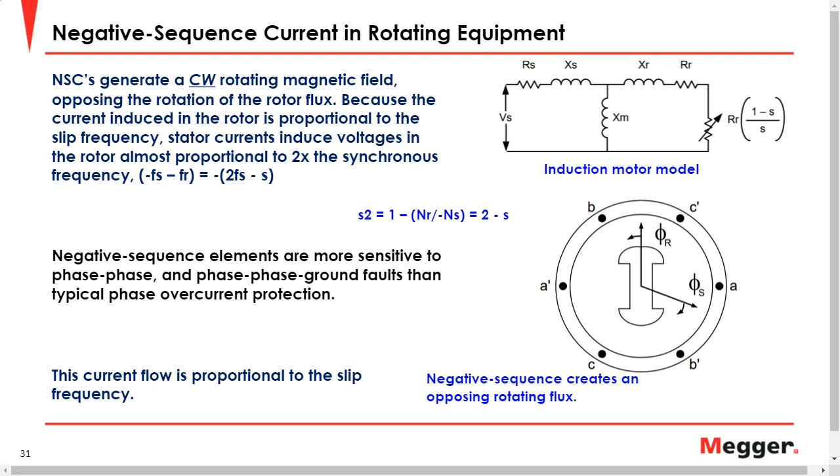You can think about that out in the field, the way you can use a ground or neutral overcurrent element versus a phase overcurrent element, where the magnitudes can be much smaller to protect you, because those things should never be very large in my healthy running system. That's really what it boils down to: we might have some, but they should always be very small in a healthy system. So it lets us respond before we have catastrophic failures, which is always what we want from our protection. We want to catch it early, not at smoke and fire time.